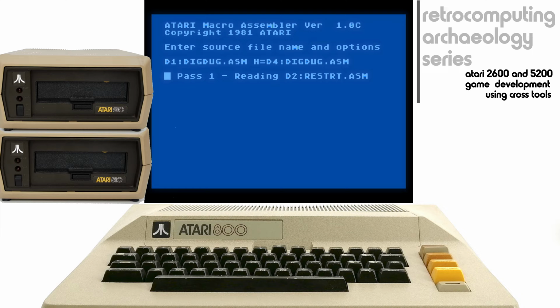As a rule of thumb, especially on these older machines running at 2 megahertz or so, it just so happens that for each kilobyte of binary that gets created, it takes approximately 1 minute of time to do so. And since we're generating a 16 kilobyte binary to go onto a 16 kilobyte ROM cartridge, that'll mean that this will take anywhere from 16 to 20 minutes to complete.